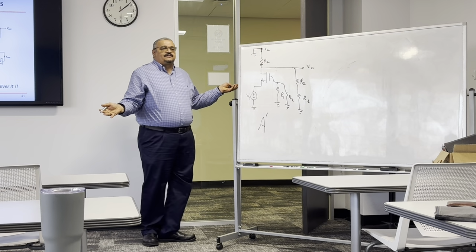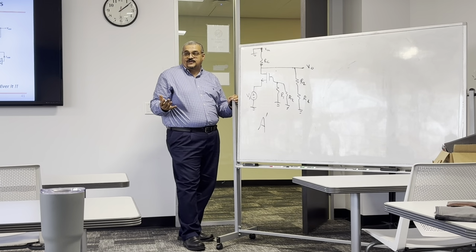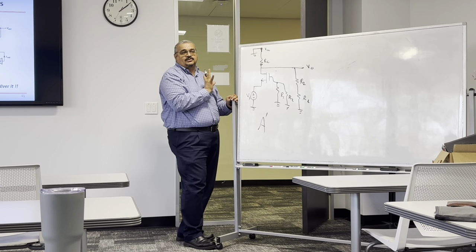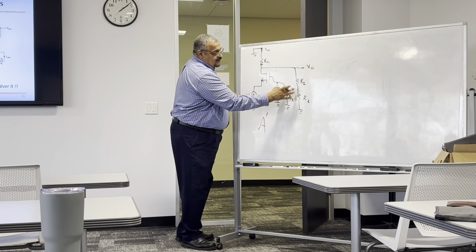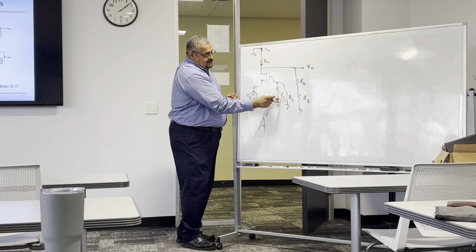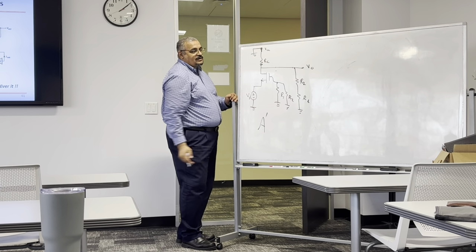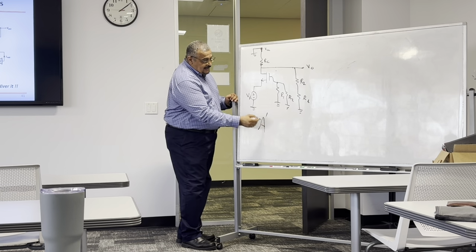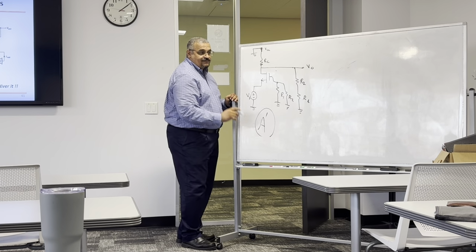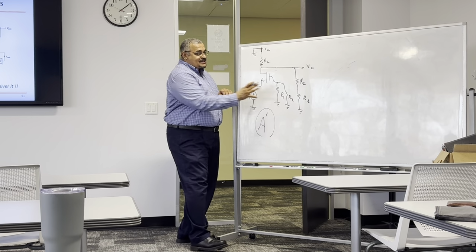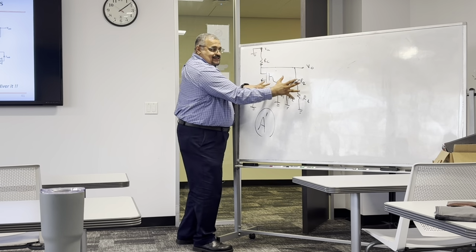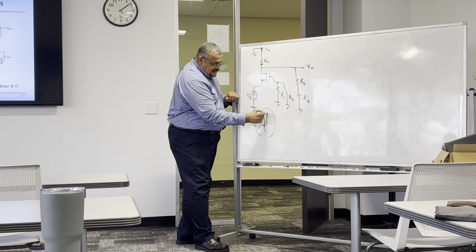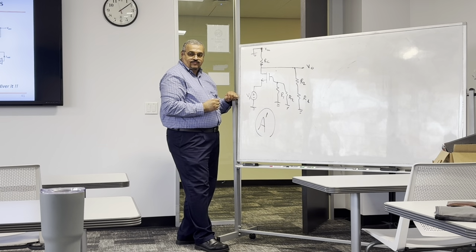Then you have a new amplifier, a new open loop amplifier. There's no feedback here. Nothing is taken from the output back to the input. You only see R1 and R2 are in parallel with this. This is R1 and R2 are connected here, and you do the analysis. The gain you are going to find here is not A sub F, it's A. But it's not A without these. It's A with these circuits in place, okay? So that's why we're going to give it another name as A dash.